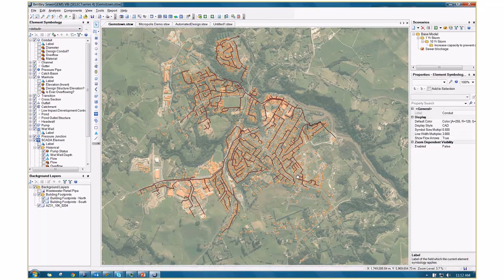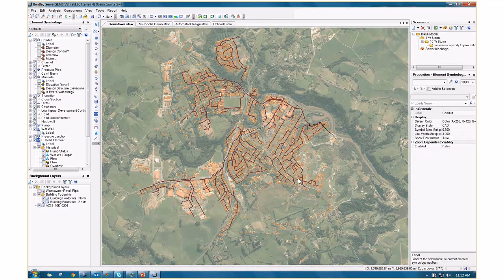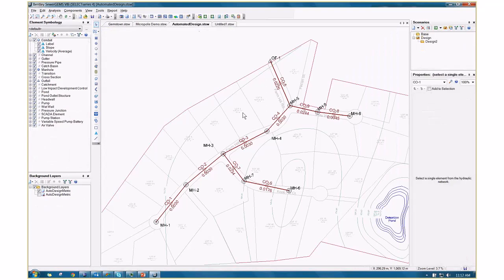Just one thing I want to clarify. For example, let us say the constraint is increase in population. So how do we build in that after 15 years, the pipes need replacement? For example, manhole 1, 2, and 3. The population is increased after 15 years. So how will it tell us that this pipe will be undersized after 15 years, so you need to replace it with a larger size?